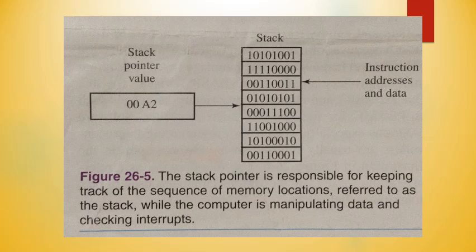Programmable memory. ROM is classified as to how it is constructed and how the program code inside of the chip can be altered. Masked ROM, usually referred to as just ROM, is a special type of memory that is permanently programmed during the manufacturing process. Masked ROM memory cannot be reprogrammed. To change the program in a system using masked ROM, you must use an entirely different masked ROM chip.